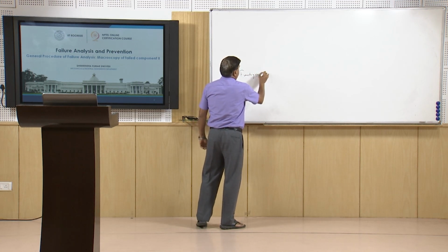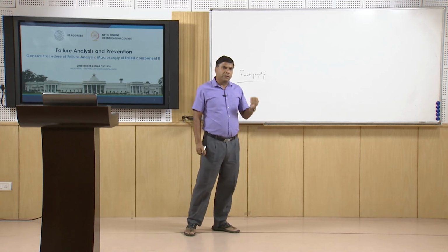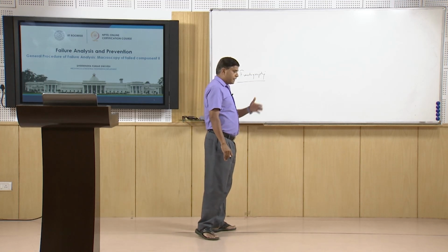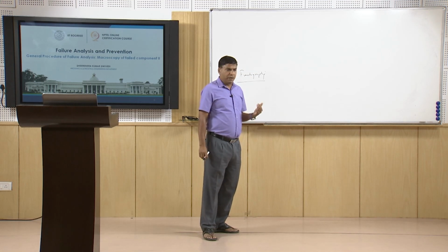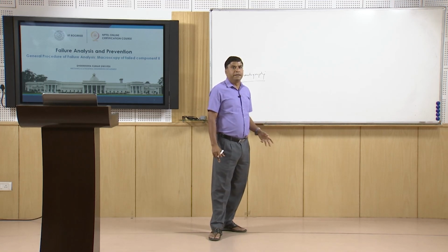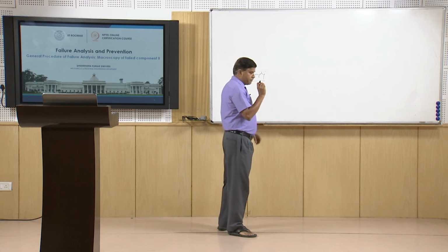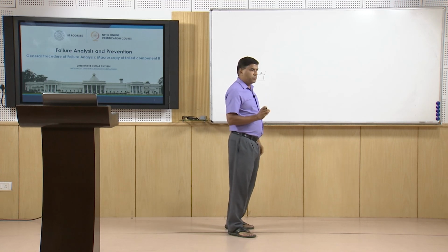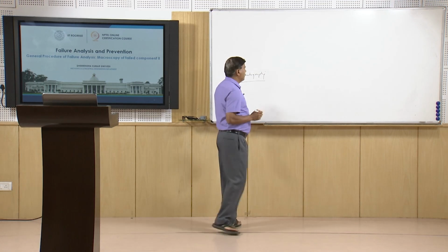You know that fractography is used for determining the environmental and loading conditions under which the fracture of a particular component has taken place. At the same time, it also helps to rule out various possibilities, whether there has been overloading, whether the material had required properties or not, or whether the discontinuities have played any role in fracture or not. But there are certain specific features which are observed on the fracture surface, which are used to make very useful inferences about the fracture.